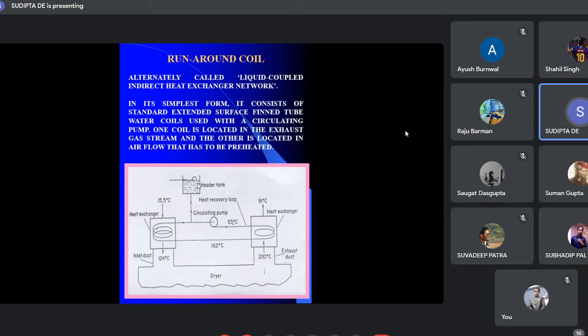So all this, the heat exchange surface on both the tubes is generally finned, has to be finned. Otherwise, you don't get effective heat transfer at all. So obviously, these are fin tubes, and with fin tubes, corresponding flow resistance will also arise. There will be a pressure drop associated with passing through the fin tubes. A design will look into each of these heat recovery, waste heat recovery designs, a very interesting engineering challenge.